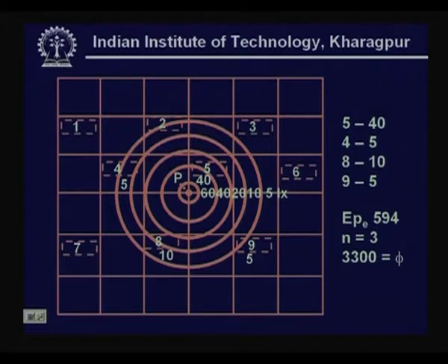It shows a rectangular space which is divided into a number of grids, and in this particular example each luminaire, marked 1, 2, 3, 4, 5, 6, 7, 8, 9, has a total flux output of 3 lamps, with each lamp having a flux output of about 3300 lumens.